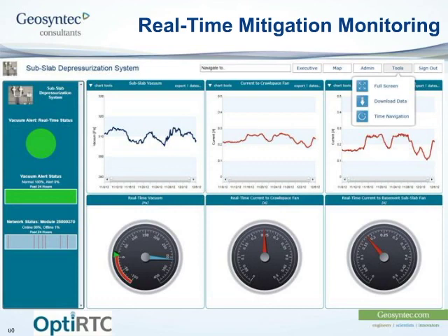We've also developed systems for real-time monitoring and control, where we can monitor the vent pipe pressures and vacuums and have variable speed drives on the fans to increase them automatically if there's a particularly windy day where that's needed. Next slide.